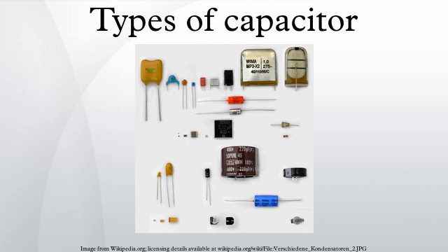Dielectric absorption occurs when a capacitor that has remained charged for a long time discharges only incompletely when briefly discharged. Although an ideal capacitor would reach 0 volts after discharge, real capacitors develop a small voltage from time-delayed dipole discharging, a phenomenon that is also called dielectric relaxation, soakage, or battery action.